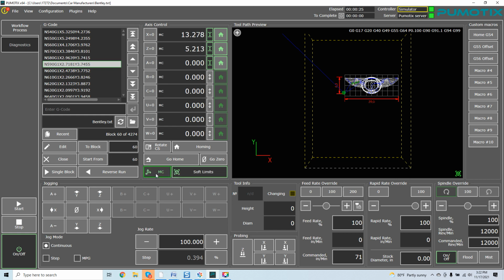And if we look at the machine coordinate position, I'm at 5 inches, okay? Total height. I'm 2 inches above the workpiece. And it's interesting to say that because now you have full clearance, and that's why we can travel that way, and that's why Safe Z-axis, I did that video yesterday, to cover exactly how to set that up. So it correlates when you're jogging.